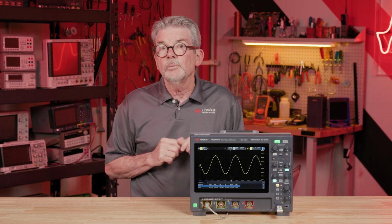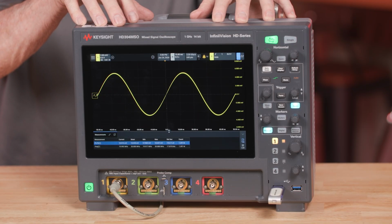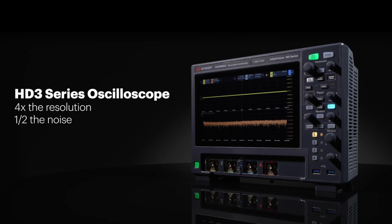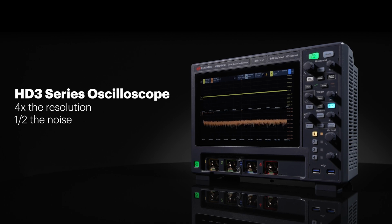In this short demonstration, I'd like to begin by showing you why the number of bits of conversion are important for accurate, low-level analog signal measurements. But perhaps more important, I'll show you why using a scope with a high sensitivity, low noise front end can enable you to see signal details that are often lost in the noise floor of other scopes. I'll be demonstrating these measurements on the HD3 oscilloscope, which provides 14 bits of analog to digital conversion. I'll be sharing additional specifications of this scope near the end of this demonstration.